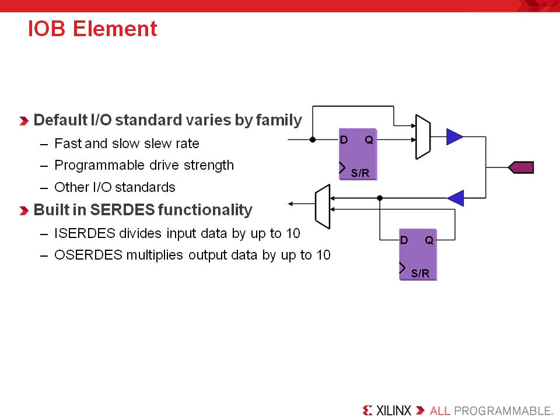Also included is the built-in SerDes logic. These resources are not incorporated with every IOB, so take the time to plan the layout of pins that will be using the SerDes functionality. To find out which pins include the SerDes circuitry, refer to the device datasheet. The SerDes circuitry can be programmed as input or output. The I-SerDes allows the user to divide by up to 10, while the O-SerDes supports multiplication by up to 10.